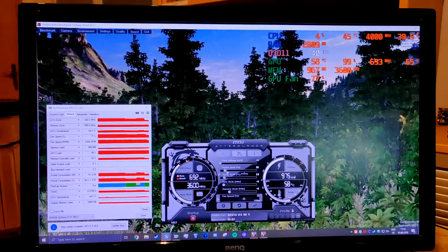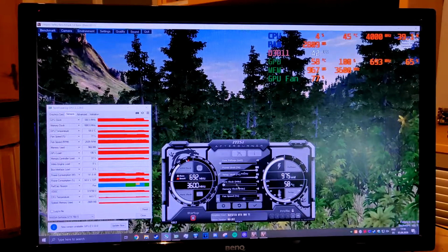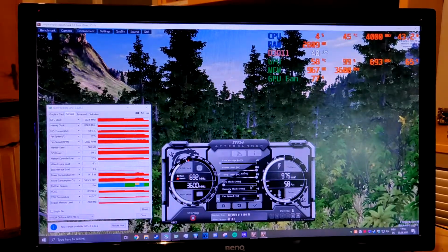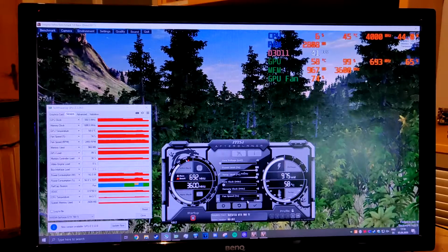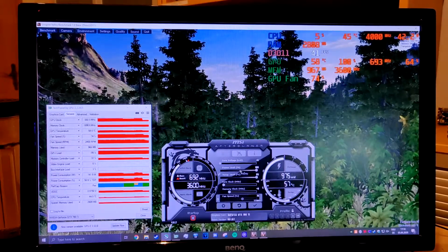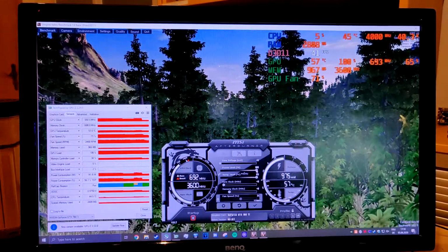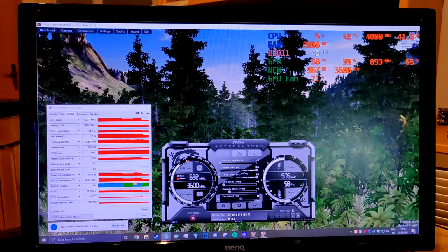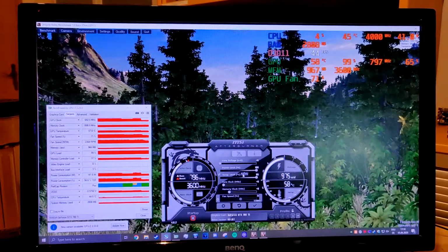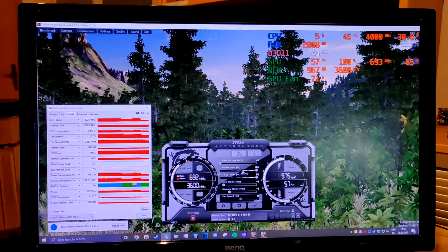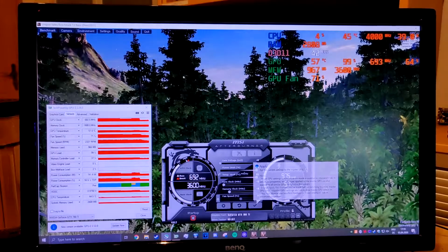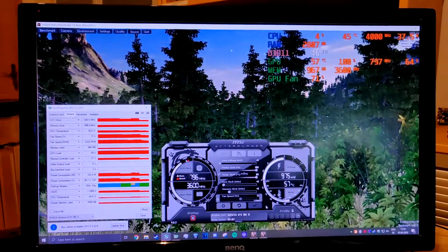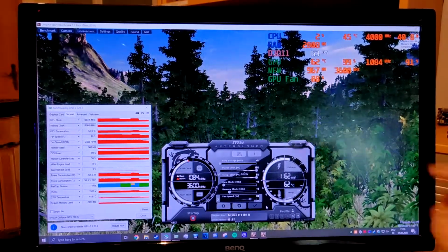If we now increase the power limit, we haven't changed any overclocking things here, like core clock, memory is still +0, we haven't touched the voltage slider. We just increase the power limit, and well, the temperature limit increases with it because these are connected together. But power is given priority, as you can see here. If you now increase the power limit and just click accept, we do nothing but change the power limit. Our voltage goes up and our clocks go up.